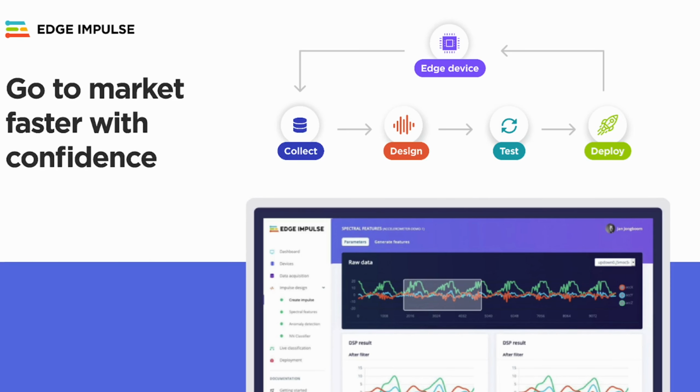The Edge Impulse Studio is an online platform that handles everything, including collecting your data from your embedded sensors, labeling the data, performing any pre-processing calculations, and training machine learning models. This end-to-end project is called an impulse. You can then test your impulse on live data with a connected sensor, and the studio will guide you through the process of creating a pre-compiled firmware or library that will run your impulse on any number of platforms. This includes your pre-processing code, your trained neural network, and any anomaly detection code that you may have so you can perform inference locally without an internet connection or on the edge.